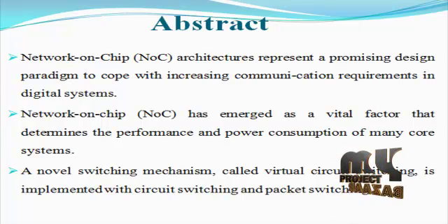The 2D mesh on-chip NoC is a popular NoC topology because of the network scalability and the use of a simple routing algorithm. However, the long distance traffic may suffer from high transmission latency. In this paper, we propose an improved design called star type architecture, in which the long distance traffic is allowed to traverse an additional second level mesh topology. Simulation results show the star type NoC architecture designs for the overall NoC design.